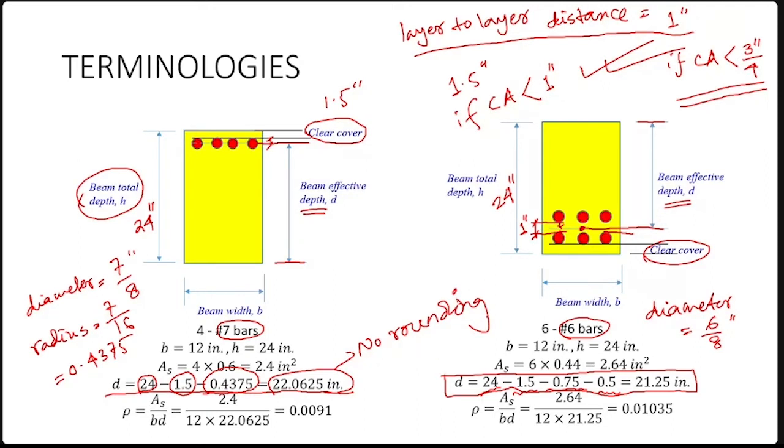We are calculating the distance from the bar centroid. The centroid is here. Can you look at the centroid point? Yes, sir. So from the centroid, you calculate this distance, the effective depth. We do this calculation by subtracting a few things from the total depth. We know the total depth; it is up to the bottom level. Then what are the distances that you need to subtract?